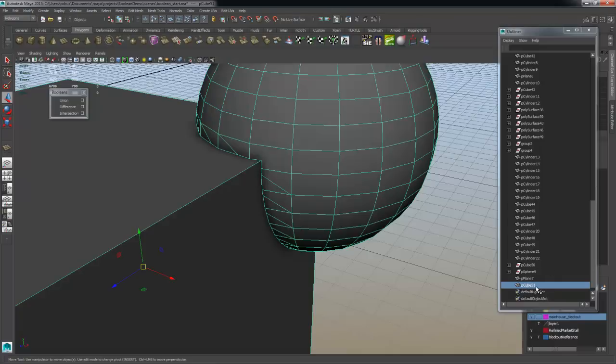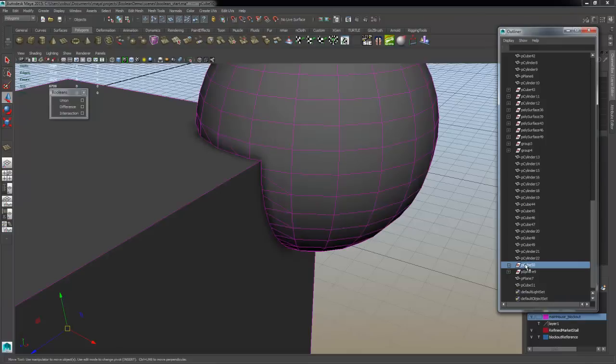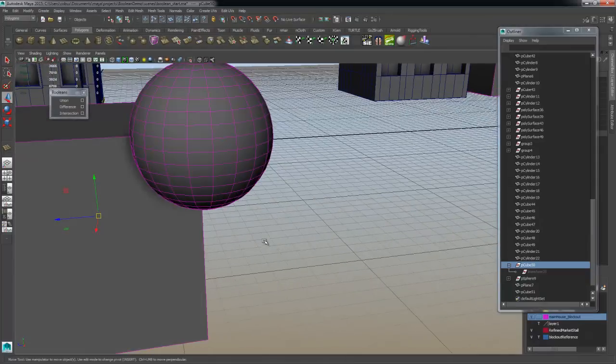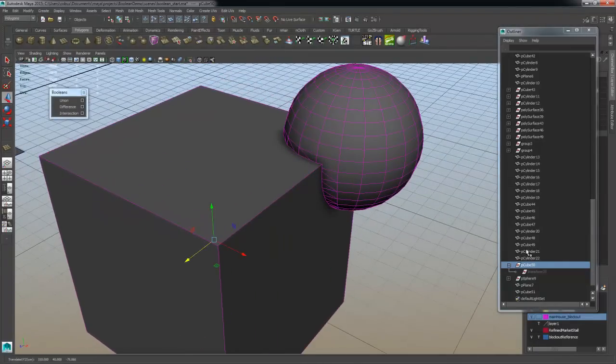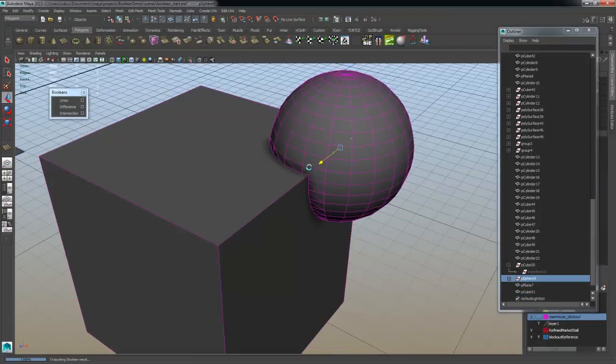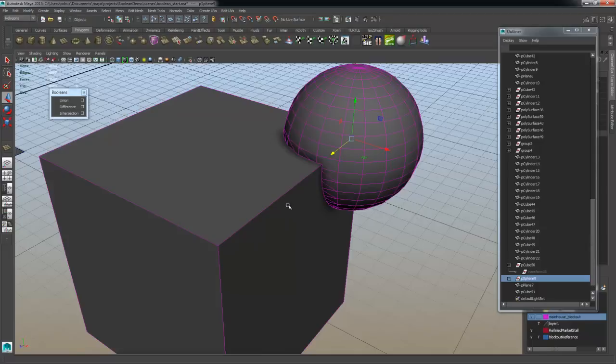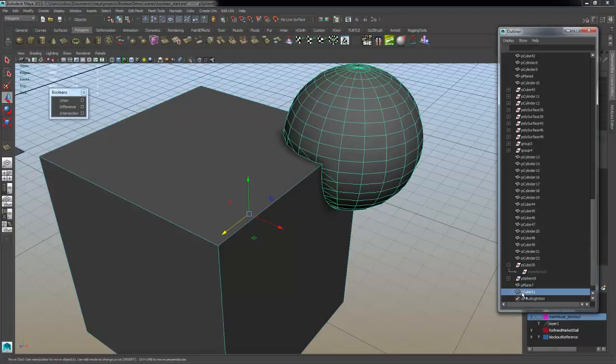It's called pCube51. What this means, essentially, is it extracted the two shape nodes and combined them together, and it connected some triangles to make sense of how it wants to connect them. At the same time, you end up with these transform nodes, the original objects, that allow you, even after the fact, to move this around, and that will in turn update the actual result of the mesh. So I can literally go ahead and move these two shapes independent from each other, and then your combined mesh would update accordingly.